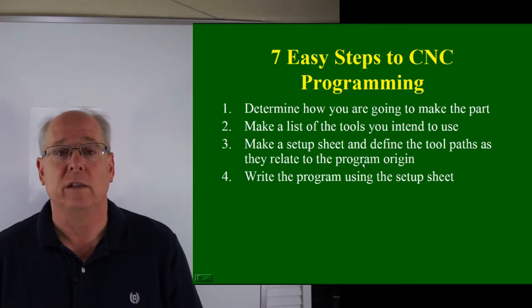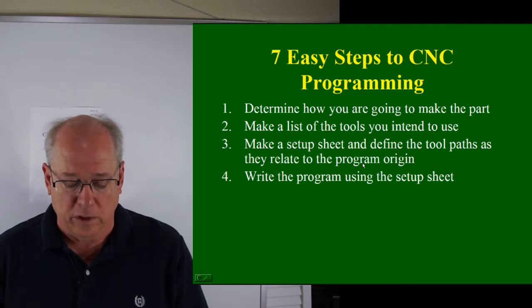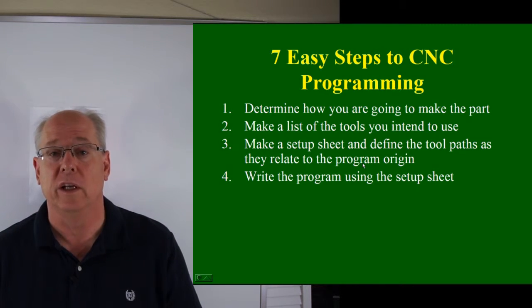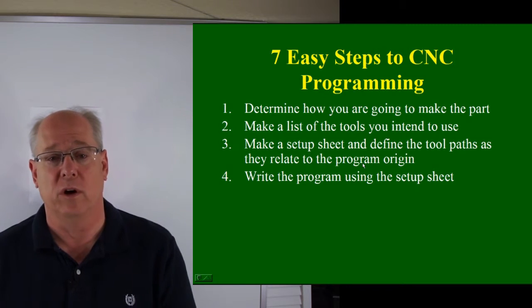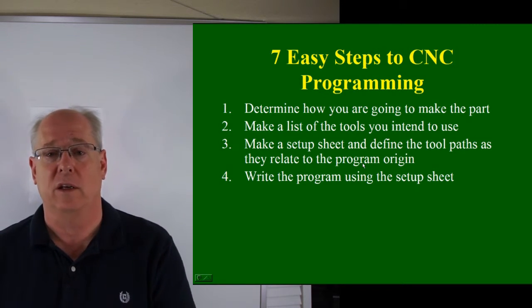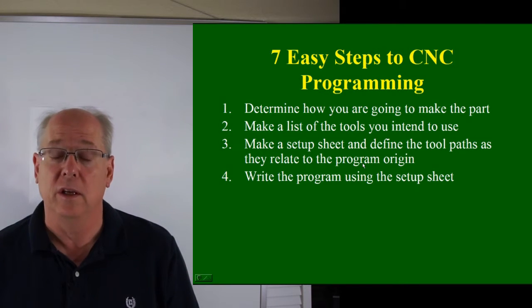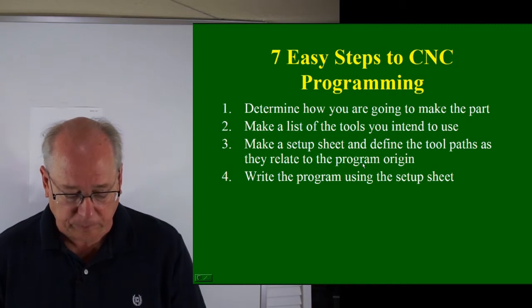Step 4 is you write your program using your setup sheet. And the reason you do this is it keeps the process organized, and it gives you a reference to go back to if you get interrupted. And if you're working in a shop with lots of people around, or you're working at home in a garage, and you've got lots of kids around, or dogs, or cats, or neighbors coming by, it's pretty easy to get interrupted, and you don't want to forget something important.